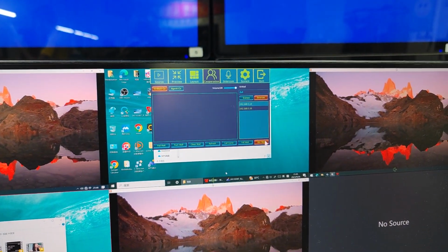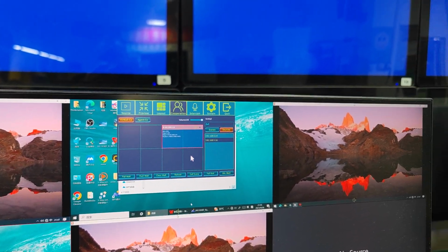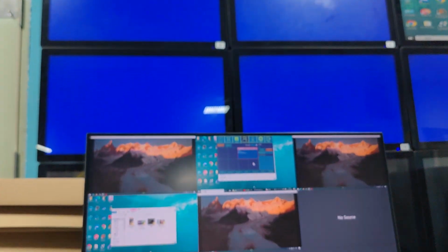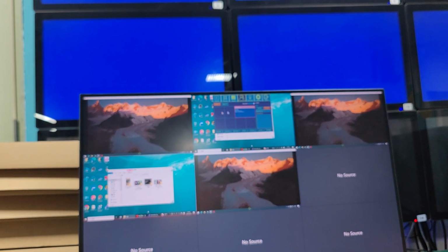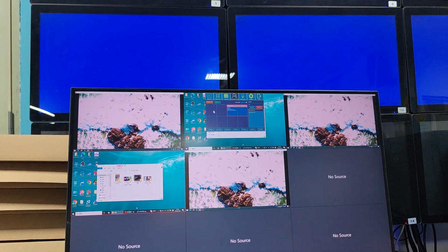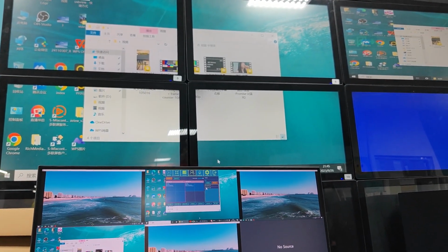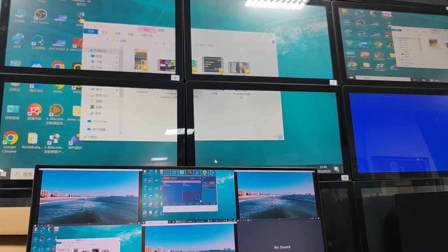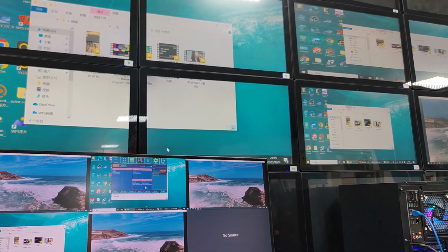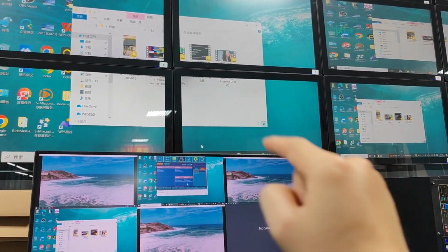So we go to the divide video wall, and now we can see we have different grids here, and we can choose a source. Now we got the 1x2 screen, but let's make a 2x2 screen video wall here. Firstly, we also need to select the source, then open the window here. Now we got a video wall here, 2x2. These two screens, we're just going to have them showing independently. Right, so now we have these two screens showing independently, and this one is 1x2, this is 2x2.